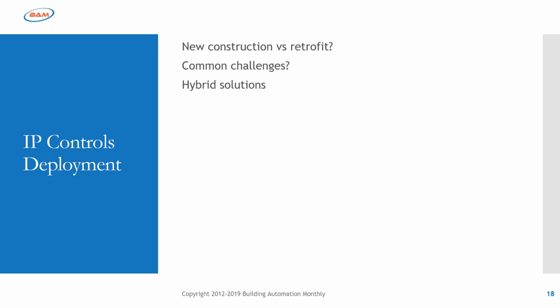If we had a supervisory device and we were using DHCP and somehow it got assigned to another subnet, and the routes still allowed, let's say we had a couple different IP address pools and we were pulling from, and we switched there, then sometimes that would cause issues with the BBMDs and BDTs in BACnet.